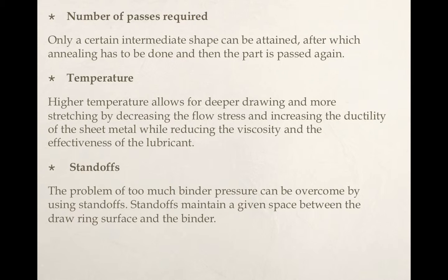And then we have the temperature. Higher temperature allows for deeper drawing and more stretching by decreasing the flow stress. This is very obvious. It increases the ductility of the sheet metal, while reducing the viscosity and the effectiveness of the lubricant. So basically high temperature increases the drawability.